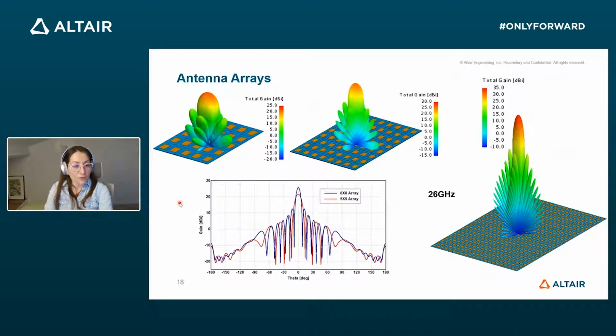ranges of frequencies. So coming back to the antenna array tool, which was recently introduced in CAD Feko, you are now able to create your antenna array based on a unit model, which you will create initially, and you will be able to duplicate this unit to create the full antenna. But what you will be able to do is that you're not only duplicating the geometry, but also you are able to duplicate the ports and sources. So this will help you gain a lot of time while designing your antenna array.